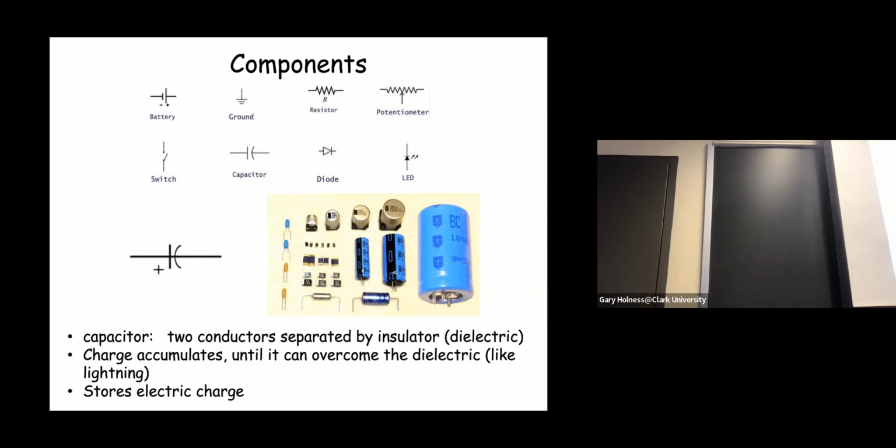What'll happen, the capacitor will charge when the voltage is increasing, and then when the voltage starts to drop, the capacitor will start to discharge, and then it'll start to charge, and it'll start to discharge. And so what used to be swinging very high and low in oscillating or changing voltage effectively will look like this. It won't oscillate as much because of the capacitor.